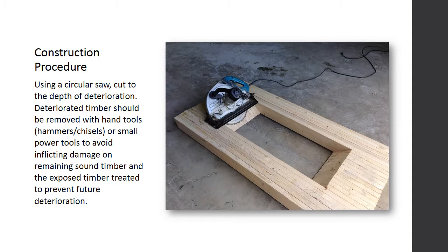Be aware that additional tools may be needed at spike locations in spike laminated decks. Deteriorated timber should be removed with hand tools such as hammers and chisels, or small power tools to avoid inflicting damage on remaining sound timber. Once exposed, the remaining timber should be treated with a surface treatment to prevent future deterioration.